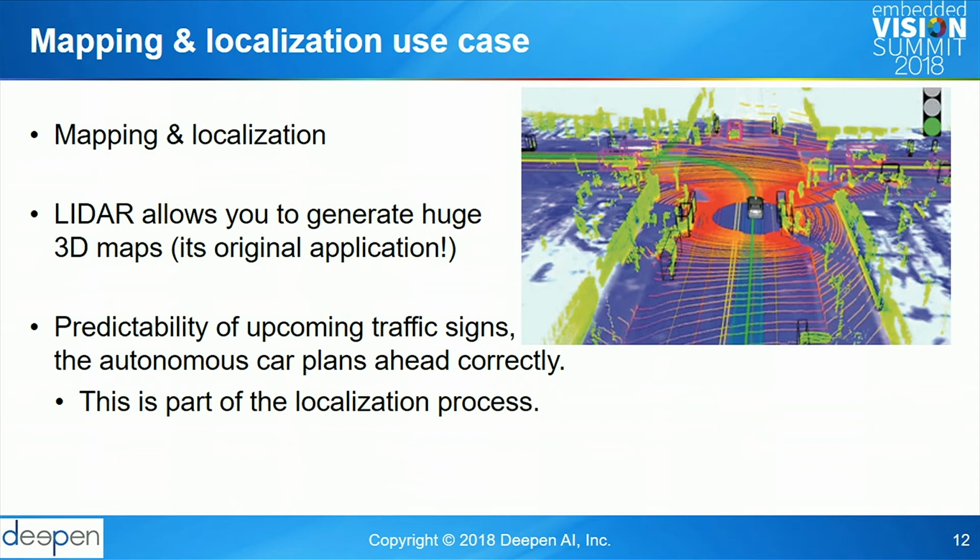Because GPS has very, let's call it, unreliable certainty. And it gets really bad when you're in urban areas. And also for autonomy, because you care about the lane that you're driving in, GPS can never give you below 5 meter accuracy. And within 5 meters, you could be on another lane, right? So LiDAR really helps with that.